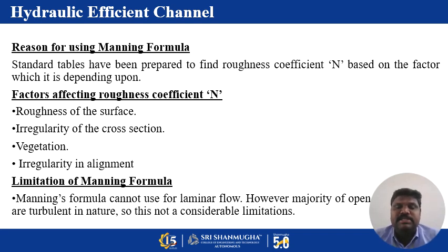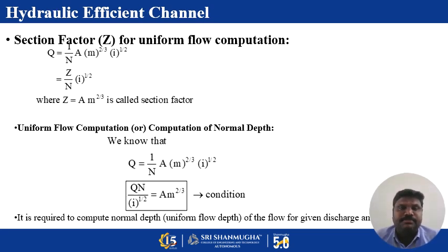Now the limitations of Manning's formula. Manning's formula cannot be used for laminar flow, because open channel flow is completely open and turbulent in nature. Open channel flow must always be turbulent. So in the case of laminar flow, we couldn't use Manning's constant; there we can use the Chezy constant.